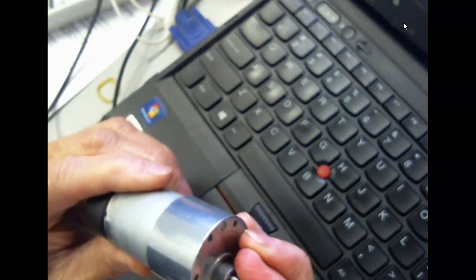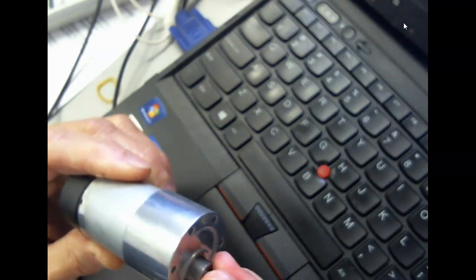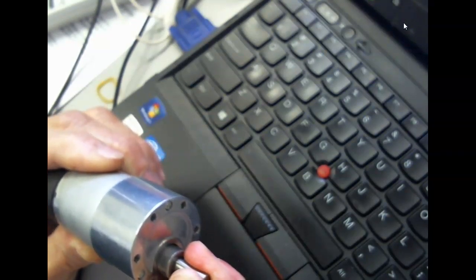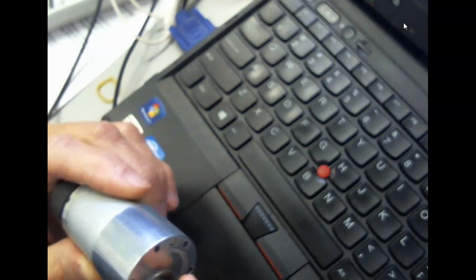And you can't turn this with your hand because it's got a 131 to 1 gear ratio. So this puts out 131 times the torque that this little motor's putting out. What happens when you increase torque? You decrease speed, right? So this right here is definitely a torque multiplier. No way in the world I'm going to stop that. Wasn't that neat? We started off by reading this, then we did the math. We calculated 16 point something, and when we actually measured it, we got 8 point something revolutions in half a minute, which is what we calculated. Pretty neat.